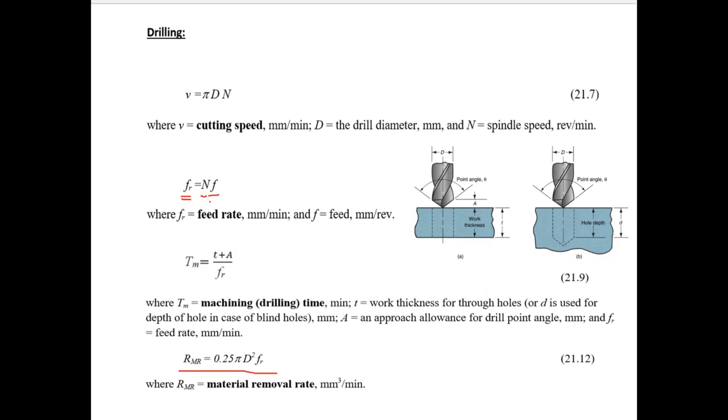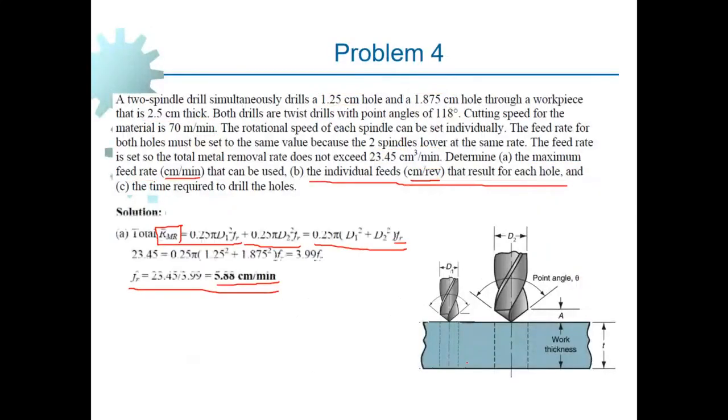And once we have got the spindle speed for each of the spindles computed, then we can make use of this equation, substituting the values of feed rate that is already computed and also spindle speed for the given spindle to work out the feed for that given, say, cutting tool. And that's what we do.